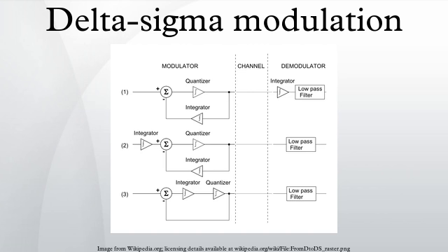Motivation: why convert an analog signal into a stream of pulses? In brief, because it is very easy to regenerate pulses at the receiver into the ideal form transmitted. The only part of the transmitted waveform required at the receiver is the time at which the pulse occurred. Given the timing information, the transmitted waveform can be reconstructed electronically with great precision.